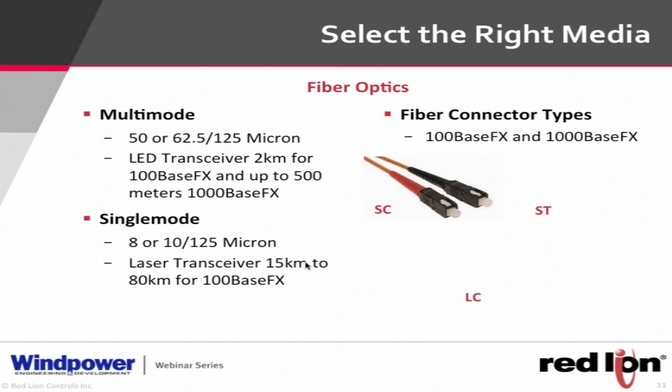And this is what fiber optics look like. Of course, you got a couple of different ends there, and we're missing some pictures, but we'll be okay. We've got multi-mode and single mode fiber connectors, and we've got the way the fiber is measured. Multi-mode is 50 or 62.5/125 micron. That first number is going to tell you exactly how thick the fiber optic cable on the inside is. If you look at the single mode at the bottom, that's 8 to 10. So it's a good bit of difference between the single mode and the multi-mode in the thickness of the fiber optic cable itself.